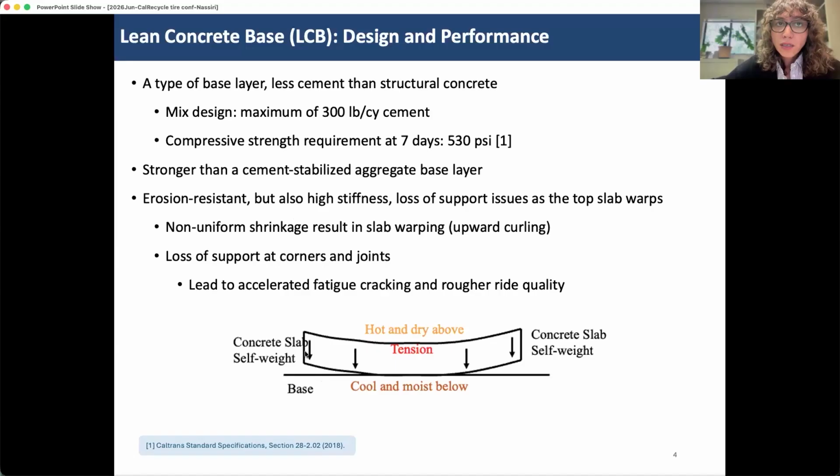So now the concrete slab is left alone in these regions to work by itself without any support from the base layer. And this causes a very critical situation where, when we have loaded axles from the truck falling on critical locations, it can either produce more and more tension at critical locations of the slab and continue to accelerate the amount of cracking that we get in the middle portion. I have a picture of this coming up, or it can result in corner breaks.